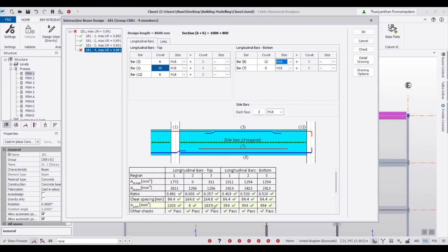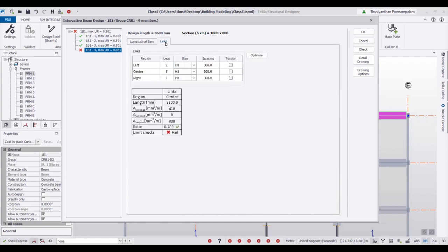So now look at the clear spacing. Earlier it was 12, right? The clear spacing we had a problem. Now it's 16, so okay. So in the clear spacing, all okay. If you want, you can reduce the rebar, maybe 9. Oh, I think 8. Anyway, you can play around with all this. It's already showing all the results here, so you can see how much is required and provide based on the required amount, right. So this is basically all our detailing rules you have to follow.